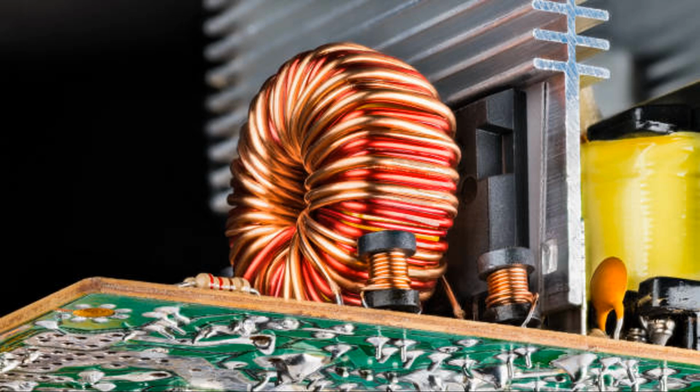4. Signal processing. A. Tuning circuits. Role. Ferrite core inductors are used in tuning circuits to adjust the frequency response of filters and oscillators. They help in selecting or tuning specific frequencies in communication systems. Benefit. Ferrite cores provide precise inductance values and stable performance, improving the accuracy of tuning circuits.